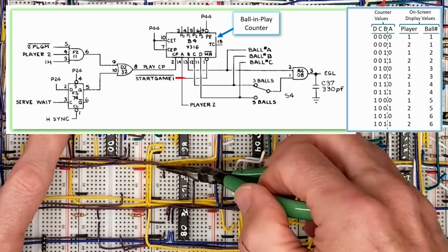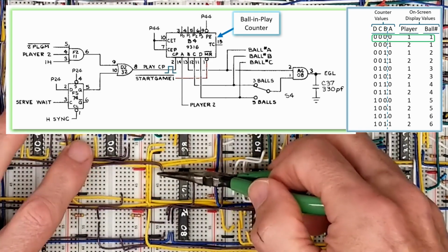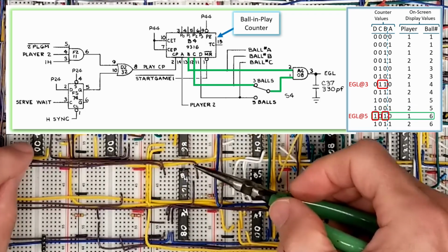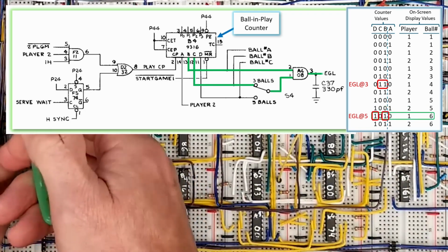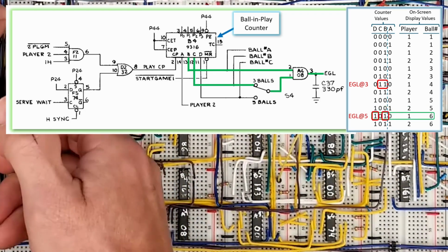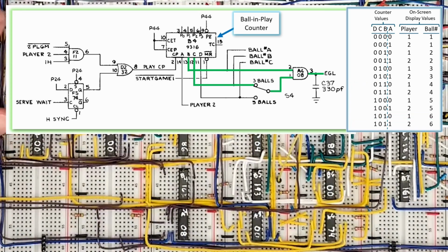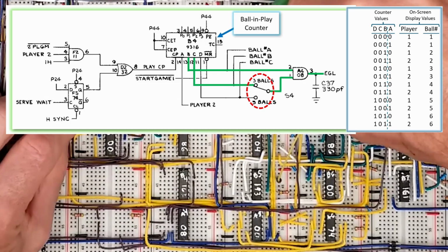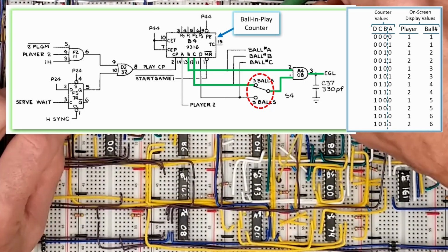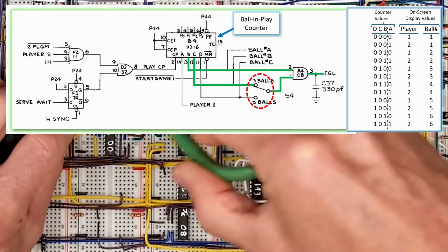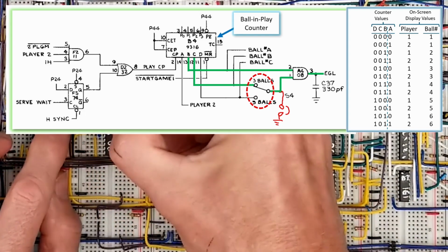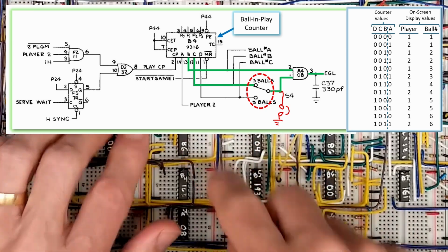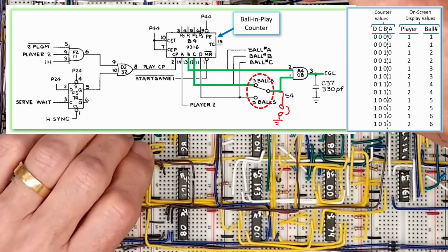The counter is reset when you start a game and counts up until the ball in play reaches either 3 or 5, depending on switch S4. This brings up the end of game line and places the machine into attract mode. Switches aren't really necessary for onboard configuration since they rarely change, so we'll be using jumpers on the retro board. Here we'll add an extra ground post for testing. Grounding this line will give you balls forever, which I'm sure is going to be the name of a future Bond movie.